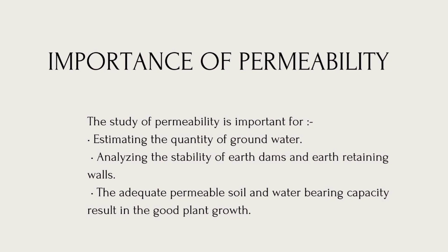The importance of permeability of soil is as follows. Permeability influences the rate of settlement of a saturated soil under load. The stability of slopes and retaining structures can be greatly affected by it. The design of earth dams is very much based upon the permeability of soil used. The filters made of soils are designed based upon their permeability.